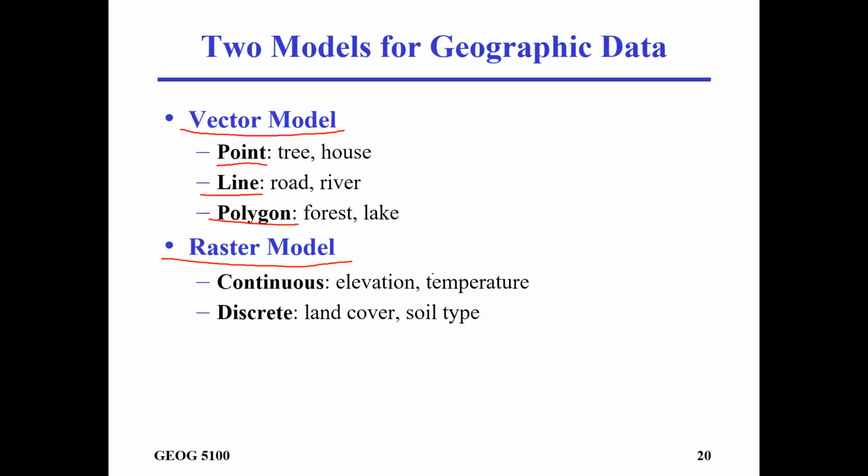But when we're using remotely sensed data to address geographic problems, there is no so-called point or line or polygons within our image, because each pixel can be occupied by multiple things. Within each pixel, there could be a tree, a segment of road, and maybe there is also a small building. So you cannot differentiate different real-world discrete objects in a raster model.